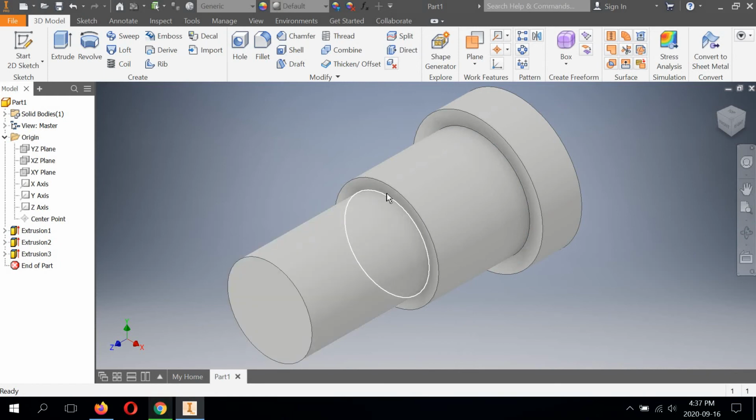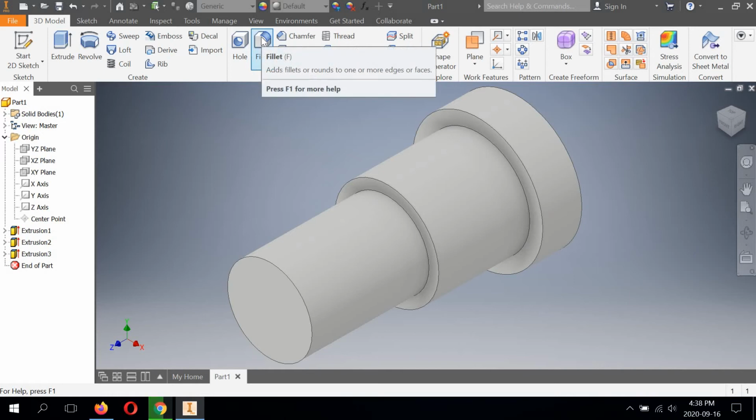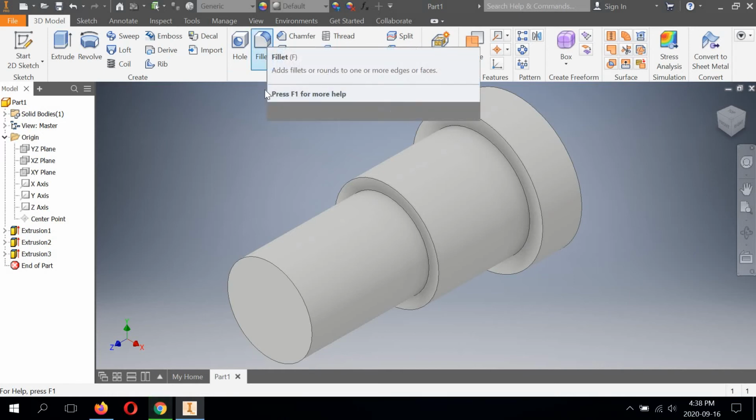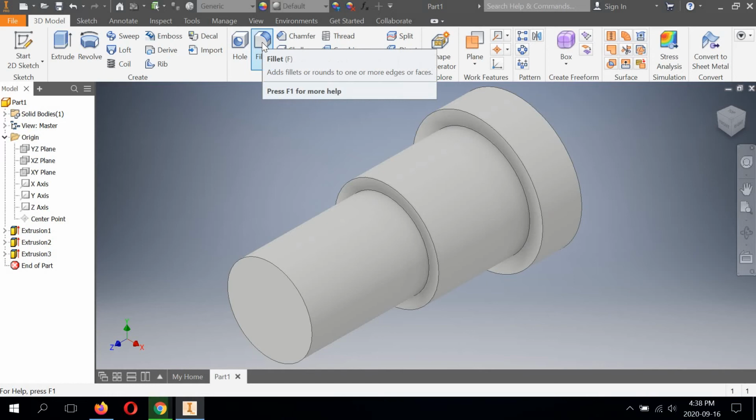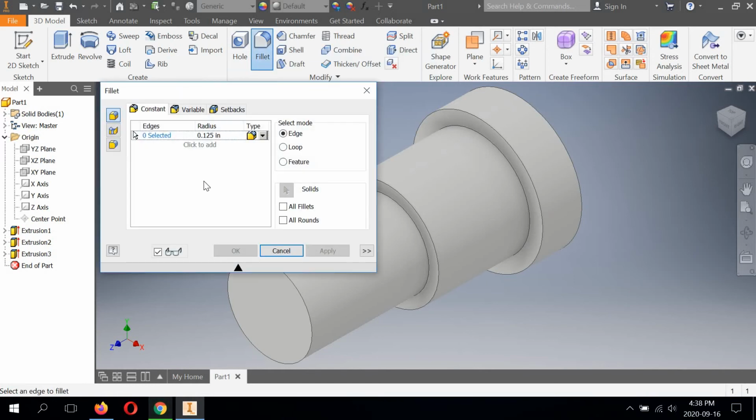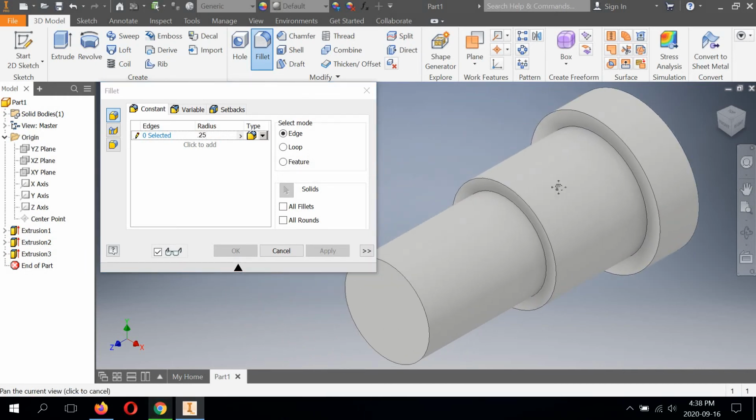There's a radius in here if you look at your sheet. And this is also known as a fillet in Mechanical up here. And it shows the radius picture. So we're going to pick fillet. And we're going to input the fillet. It's listed on the screen as 0.25. So we're going to click this, click 0.25, and then I'm just going to pan this to the right with my wheel so I can see it.